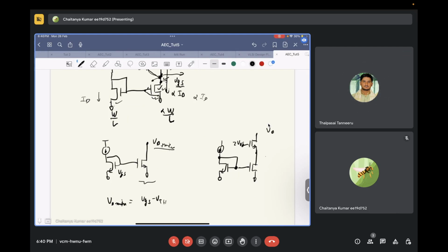Now, what happens over here? Then VG should be VG plus VTH. Sorry? Then what should the minimum gate voltage be? It should be VD min plus VTH, no, sir. I'm talking about the VD, that is the drain voltage. Drain voltage of which transistor? As this VD starts going down, which transistor will go into triode first? Which of these three transistors?